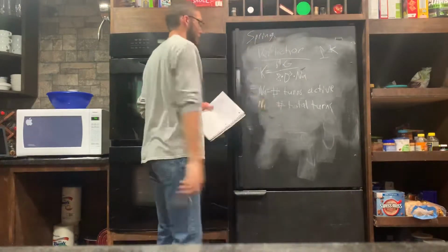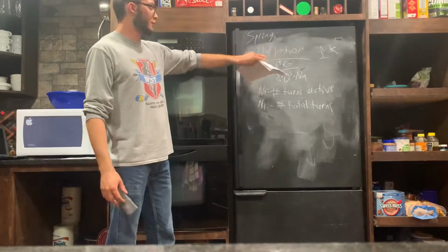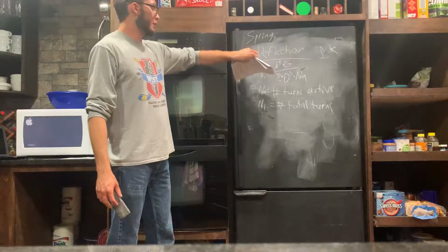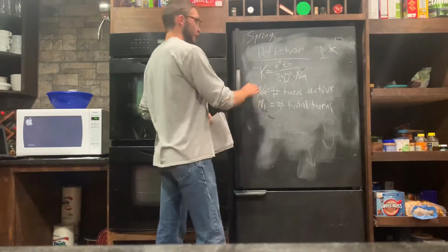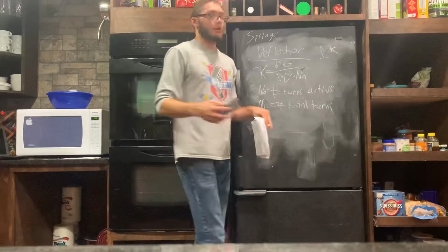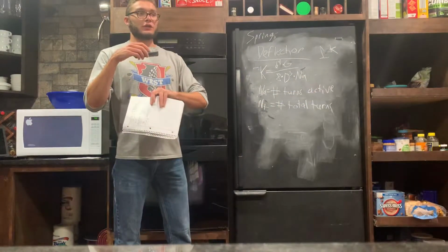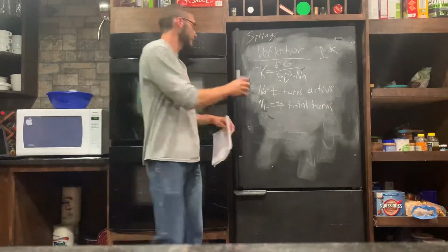So that's pretty much it for deflection. You just determine deflection using your coil diameter, wire diameter, and the number of active turns, because the active turn number is how much of the spring is actually going to affect the force.